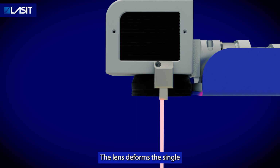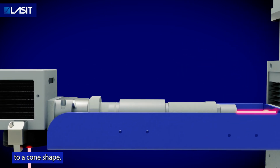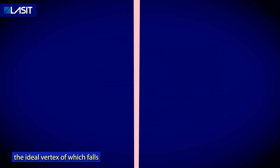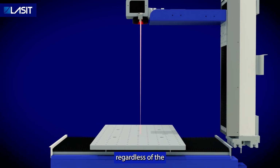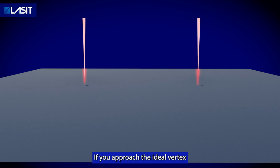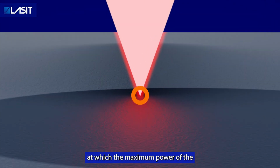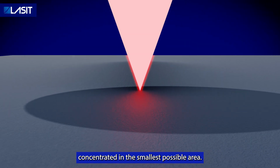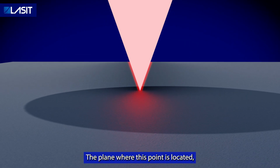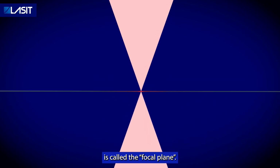The lens deforms the single laser beam, changing it from a cylindrical shape to a cone shape, the ideal vertex of which falls on a plane parallel to the plane of the lens, regardless of the exit angle of the lens. If you approach the ideal vertex of the cone, you can see the point at which the maximum power of the laser beam is concentrated in the smallest possible area. The plane where this point is located, i.e. where the laser vertex falls, is called the focal plane.